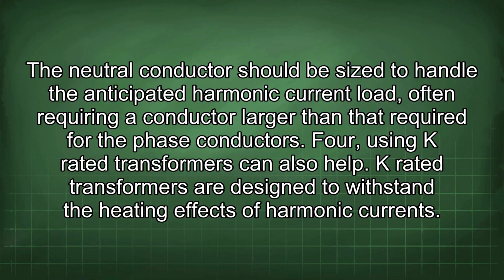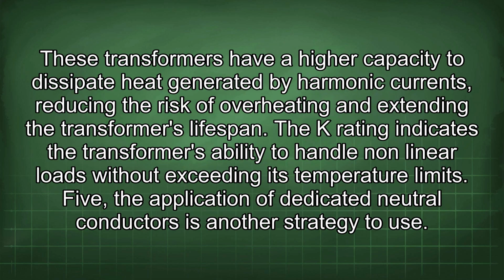Using K-rated transformers can also help. K-rated transformers are designed to withstand the heating effects of harmonic currents. These transformers have a high capacity to dissipate heat generated by harmonic currents, reducing the risk of overheating and extending the transformer's lifespan. The K rating indicates the transformer's ability to handle nonlinear loads without exceeding its temperature limits.